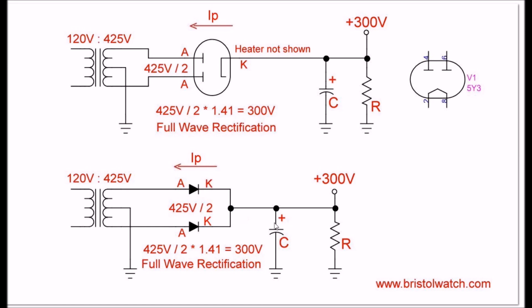So electrons are pulled from the positive side of the capacitor, but cannot return because the diodes only conduct in one direction. One student, for example, described a diode as an electric check valve, and it is. Current flows one way and cannot come back. The only way you can really return is either through the resistor or simply short out the capacitor. You'll discharge the capacitor only through the load.